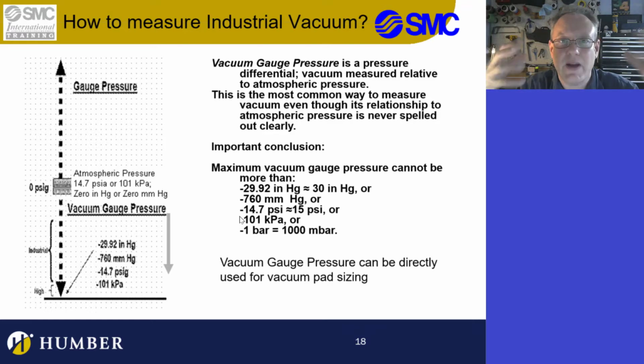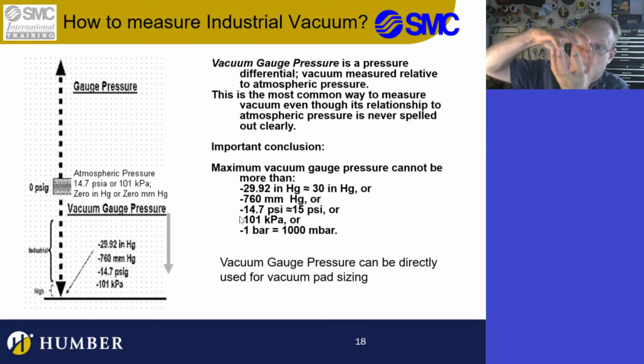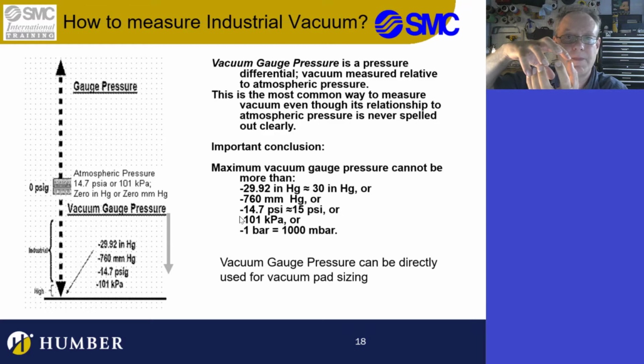It's the differential pressure. So the differential pressure is actually the pressure creating the force. So when we look at vacuum, we measure vacuum in two different ways. One is psi A, the absolute vacuum. Okay, so that's 2 psi A in this magical little ball here.